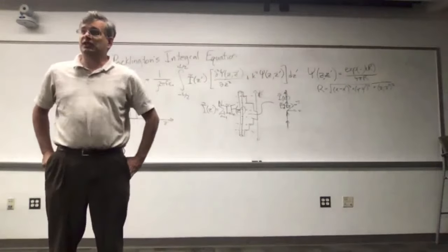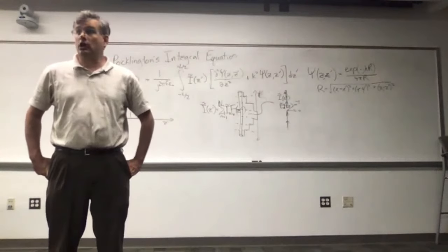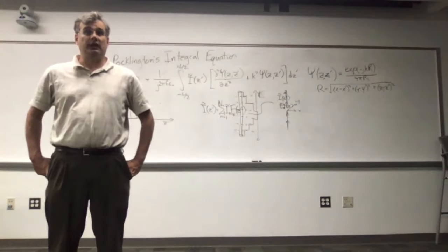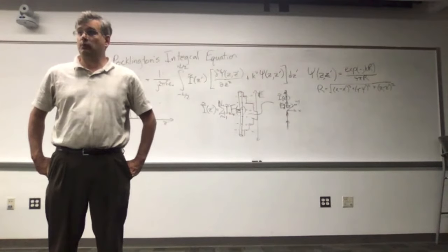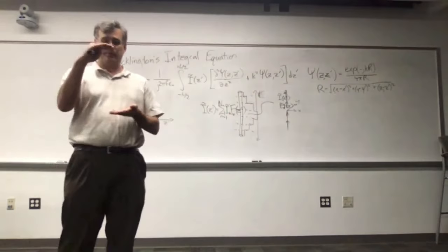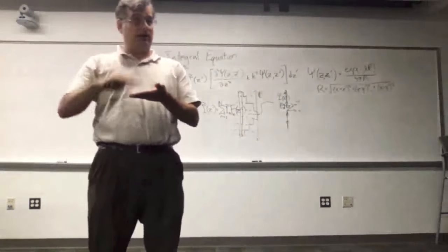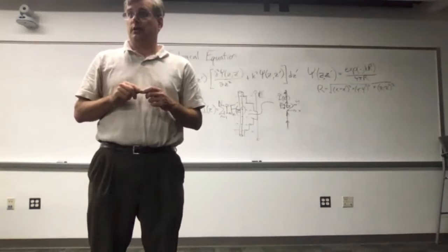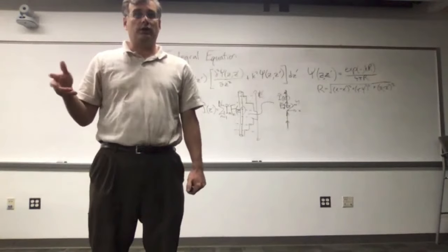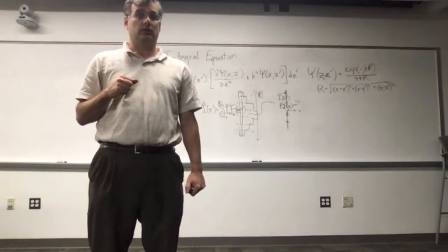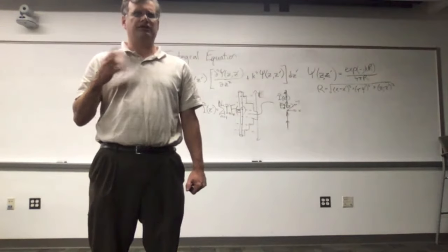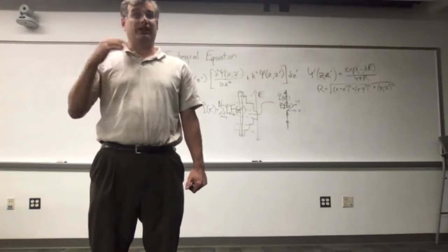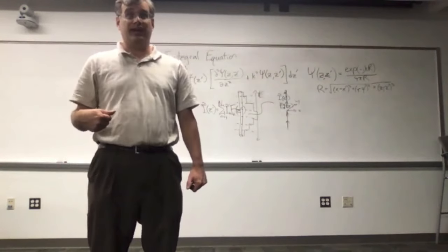And in fact, what we'll see, and what you'll see when you start playing around with the code, is that up until a point, this thing can be very sensitive to the number of samples in your simulation. If you have a half-wave dipole, you've got a half wavelength of wire to break up into little chunks. And if you only break it up into 3 chunks or 5 chunks, you're not going to get the right answer. But if you use like 9, 10, 11, you'll get a really nice answer. If you use 20, you'll get a great answer that won't differ that much from your 10 sample answer.